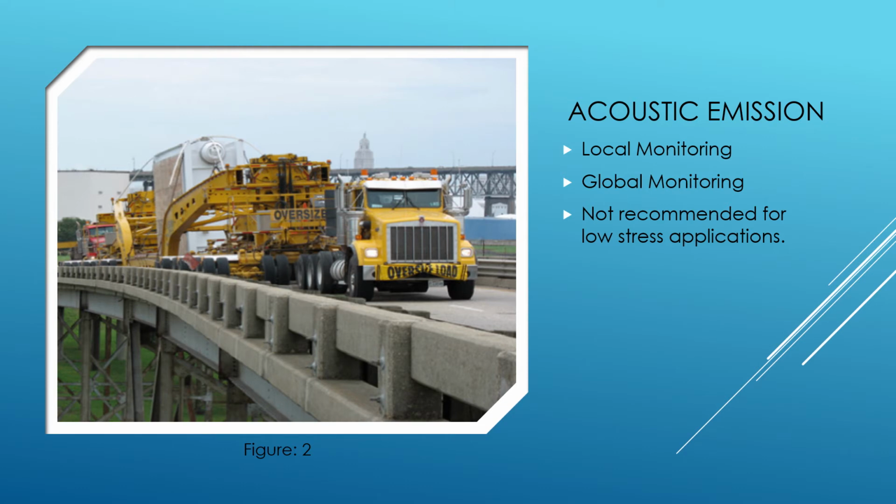Strategies of AE monitoring include local and global. Global monitoring assesses an entire structure's integrity, while local monitoring assesses a specific location of the material. Some of the disadvantages of acoustics are the complexity of the noise filtration process. This system is also not recommended for bridges that are not under frequent high-stress applications.